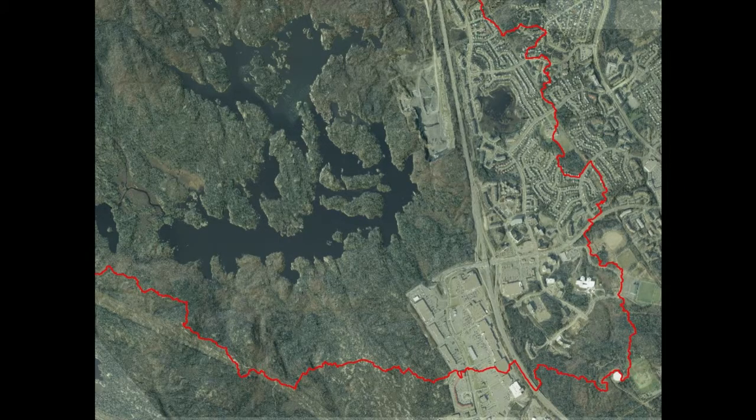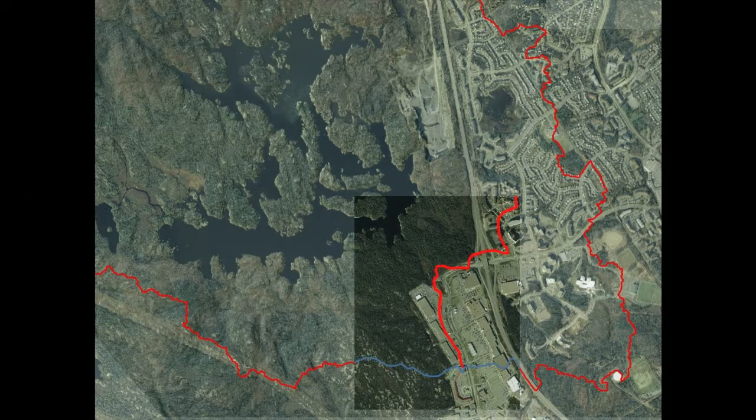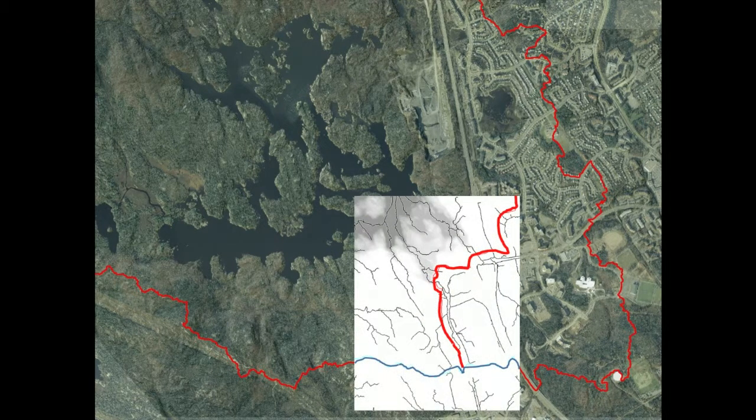When we look at a data set at this resolution, we'll see that this natural watershed actually covers an urban area as well as a rural area in this particular example. When we look at it much more closely and apply the LiDAR drainage vectors and transpose the urban drainage infrastructure, what we find is that the true watershed is actually over here. And we can see that illustrated here. So there is a discrepancy between the surface drainage and the anthropogenic drainage. And I think that needs to be borne in mind.